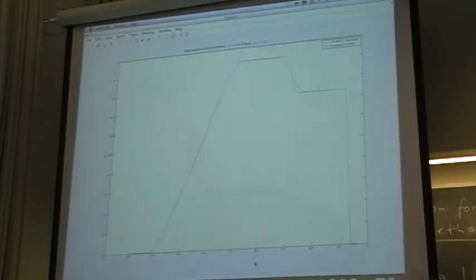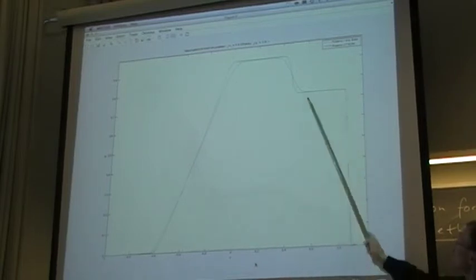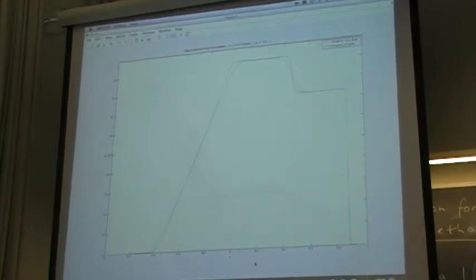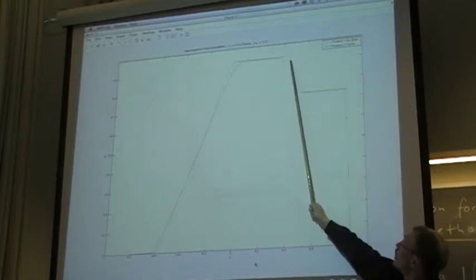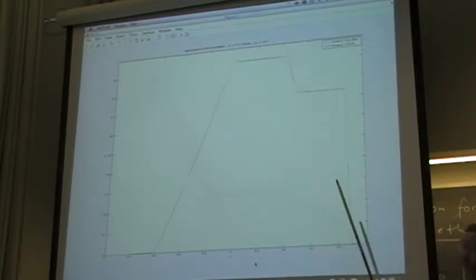And there you see also the TVD, so it's the second order TVD, but we also use a higher order method in time that we shall see in a minute. So here at the shock we don't see much difference, but at the contact discontinuity we see a big difference. Using the same grid size but using MUSCL gives a considerable improvement of the resolution of the contact discontinuity.